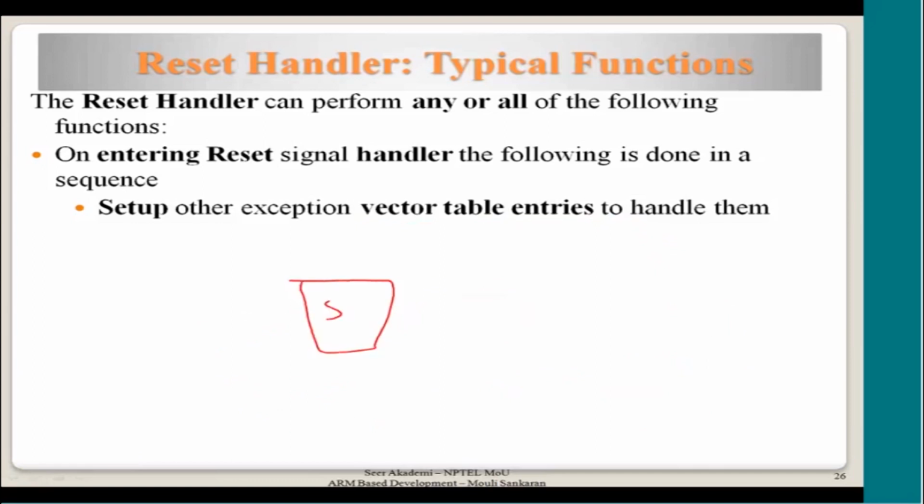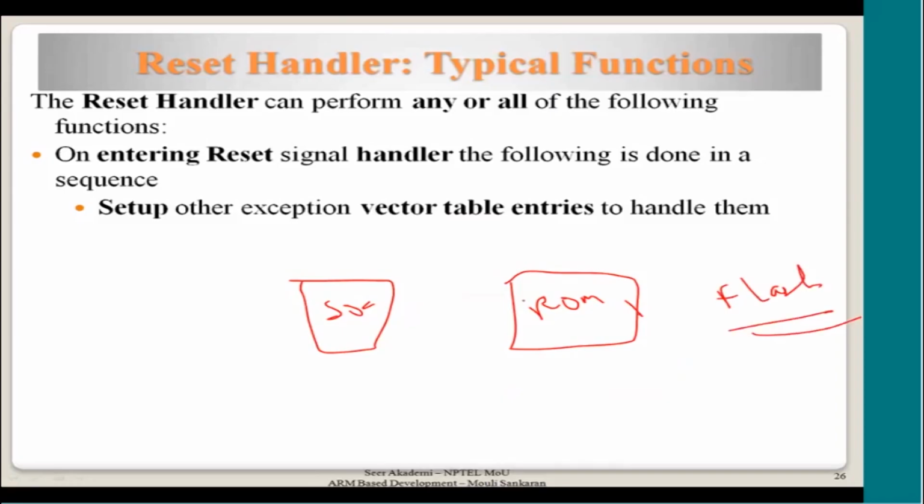This is an ARM system SoC. Okay, what you normally do as a system programmer is you put a ROM or a flash, which will have the contents even when the power is lost and then when power comes back. So initially, to start with, maybe the address 0x0 will be pointing to a location which is already loaded with some value, which could be a ROM location. Later on you may use an MMU or some circuitry to change this to a RAM location. This will involve some more knowledge on how the different memories are handled in a real system.